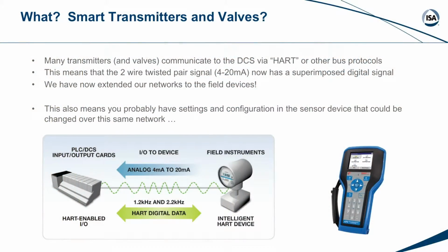Now let's talk about, if you go back to the 4 to 20 milliamp conversation we had with that current loop, right? So you had this twisted pair of wires that ran from the transmitter to the system. Here, I'm going to say 15 plus years ago probably, people started to say, I bet we could superimpose a digital signal on top of that and get more information out of these devices or push more information to these devices. And this is where you get terms like HART, which, don't try to make me remember what that acronym stands for.